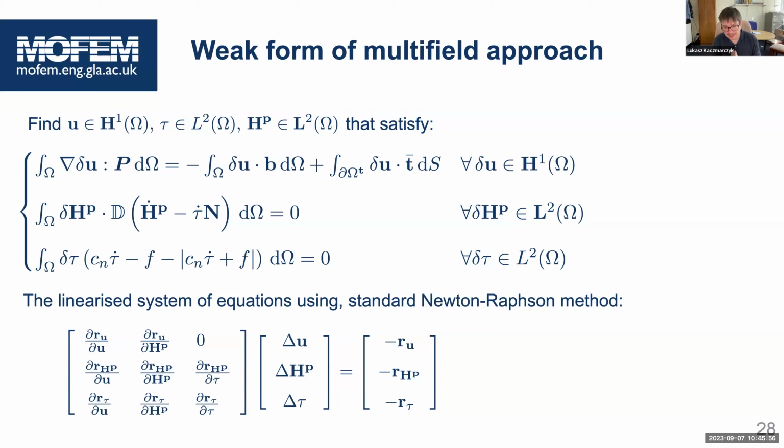Okay, which makes sense, because when the plastic front develops, you have elements which have zero plastic strain, and next to them you have a stressed element such that the plastic strain is not zero, so you have a jump on the border. That's why you have to have L2 space, because if you do not choose L2 space, you will not be able to reproduce classical plasticity results.